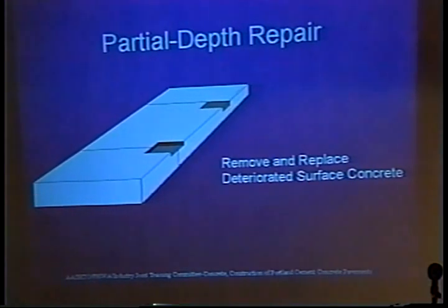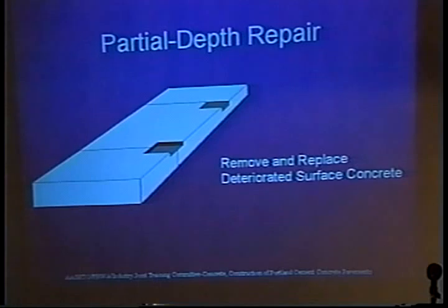But if you don't get all the unsound material out of the hole, and the asphalt guys have already talked about this as well, same thing applies. If you don't saw cut, if you don't remove all the unsound material, you're wasting your time out there. And I hate to see people wasting their time. So you got to do it right the first time.